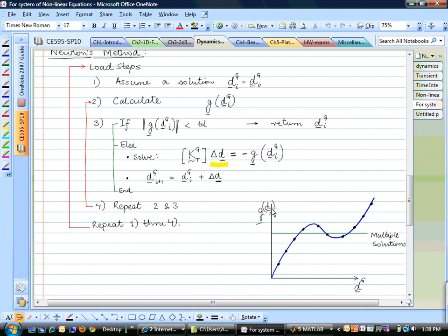So for nonlinear problems, whenever you apply all the load in one step, it can have some problems. So there is an option to set the initial step to be something like 0.1 or 0.05. What that means is you're applying only 5% or 10% of the load. And then Abaqus will just keep on increasing the load level, going from one point to the next. And within each of these cycles, it will do the nonlinear iteration. So it will do all these steps for this load, and then do all those steps for this load, and so on, keep on going.